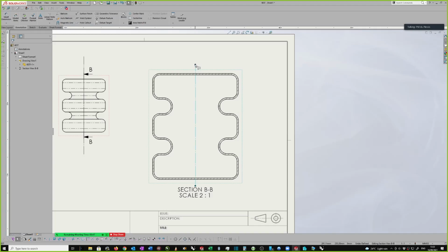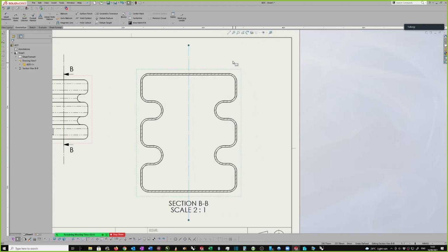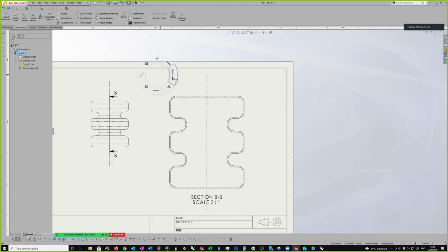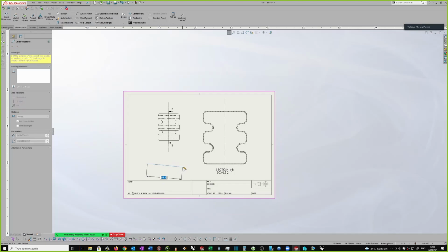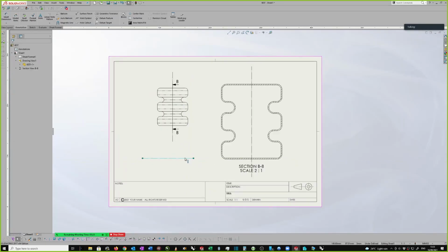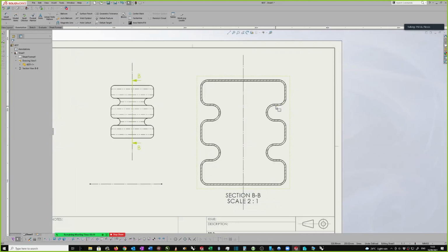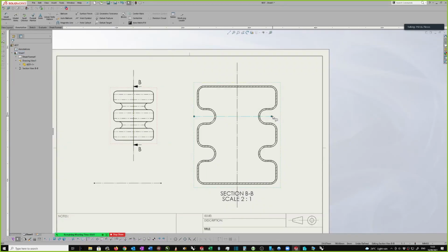So this is your center line. There are 2 things about center lines, well, maybe more, but there's certainly 2 things that are most problematic. One is we use the term center line in many ways. So I can actually create a, see what it's called. They call it a center line. It's called a center line. I can create a construction line like this, and it's called a center line. And this line here is also a center line. And I can put in a center line between here and here, which is going to be useful, what I need. So these are all center lines, but they're center lines of different types.